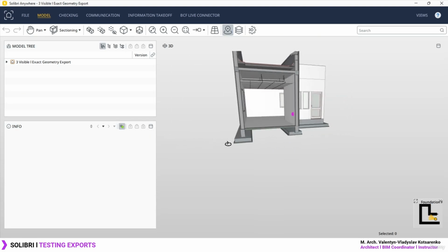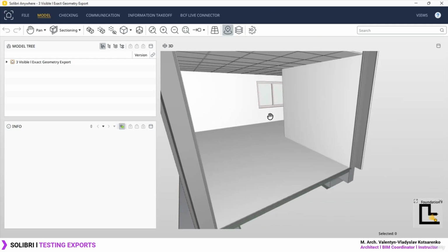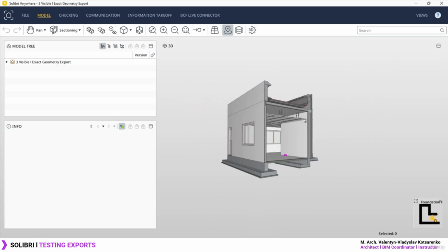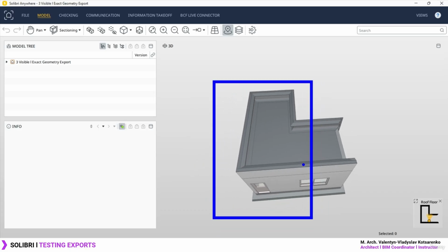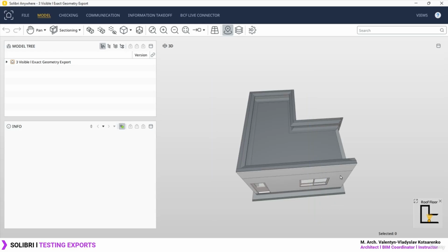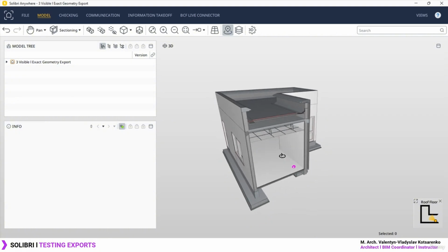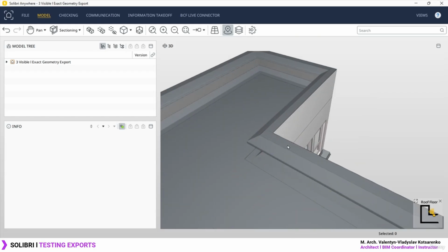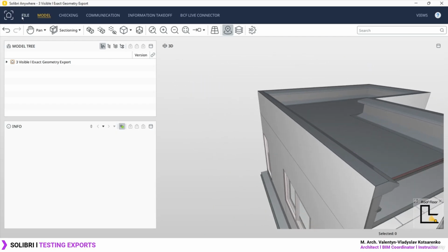So yeah, it's going to filter out the cut section, and it actually did respect the furniture. If you remember, we selected the furniture, right clicked it, and made sure to hide it. So it also respected that. So you can proceed with this quick filter if maybe you only want to export 50% of the project. Create a quick section, and that's how you can export 50% of the project if you're looking for something a little bit more limited. Okay, so it's looking good with the exact geometry. We don't have weird intersections going on over here, so that's good to know. Let's proceed with the next model.